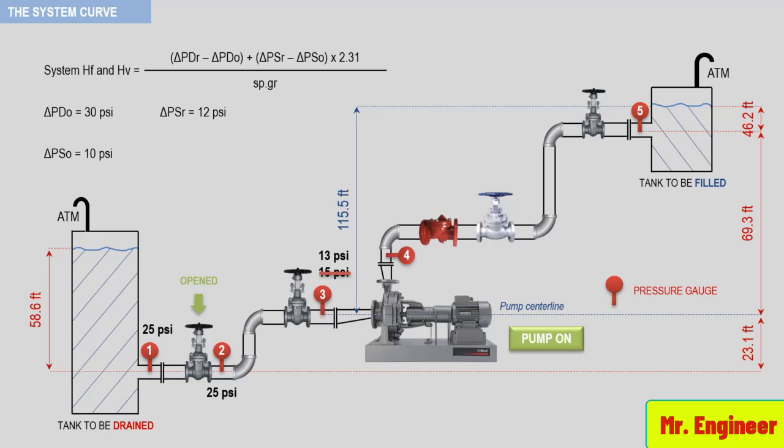The 94 feet indicates that the pump can generate about 40 psi. Recall that to convert head into pressure, we multiply the head by the specific gravity and we divide by the conversion factor 2.31. So here 94 feet times 1, which is the specific gravity of water, divided by 2.31 gives 40 psi.